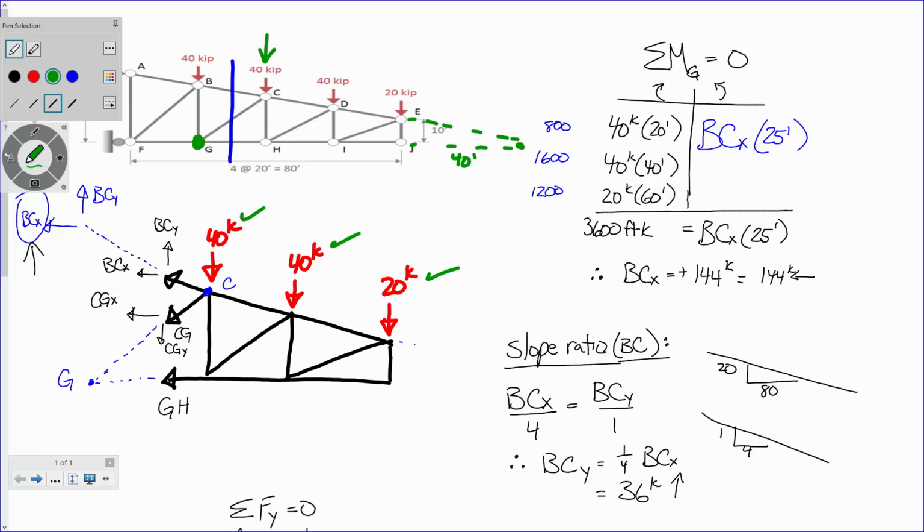All right. Does anybody have any questions about this problem? Now, we have another truss problem coming up where we're going to do truss deflections. And if you all remember from structural analysis, in order to calculate truss deflections, you have to use the unit load method. You put a 1 kip force on there, and you have to do 2 truss analyses. So we're going to have more experience with truss analysis. So don't worry, we'll have plenty of experience. All right.